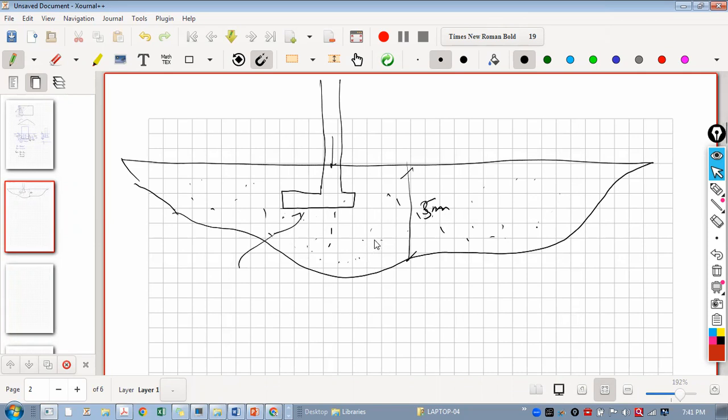So there is a possibility that whenever you are filling the soil in this valley region, the compaction is not done properly. And if the compaction is not done properly, then there may be air voids here like this. Due to this load and these air voids, the foundation gets settled. And there is a possibility of differential settlement and finally the collapse of the building. So you should take great care in this kind of foundation design.